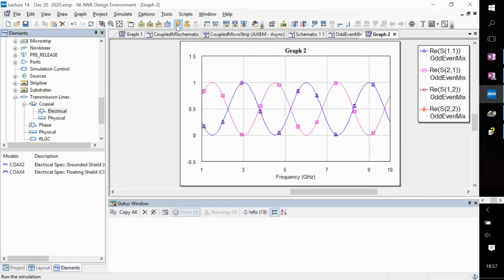Okay. So when working with these kinds of matched or balanced networks related to coupled things, these phases become important if you're worried about even and odd mode, because it's just the phase which determines whether something is an even mode or an odd mode excitation. So you have to keep cable lengths and transmission lengths identical if you don't want any weird mode mixing to happen.